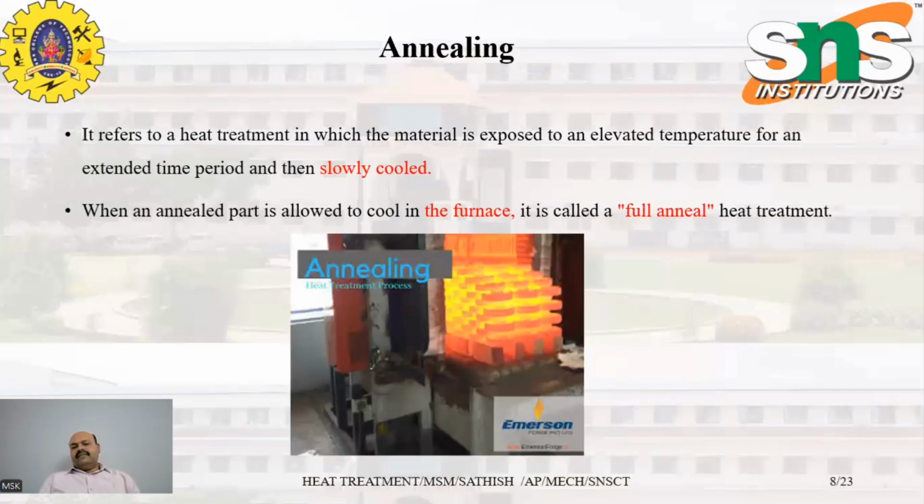So annealing is a heat treatment process in which material is exposed to an elevated temperature for an extended period of time and then slowly cooled. When the annealed part is allowed to cool in the furnace, it is called full anneal heat treatment.